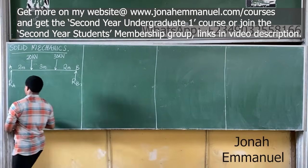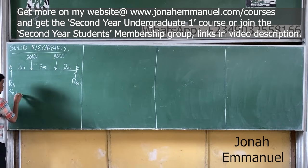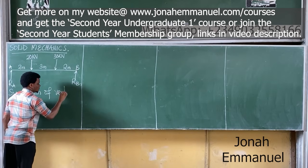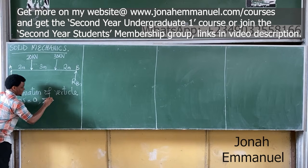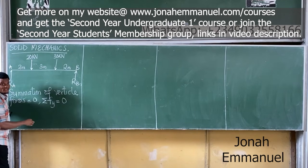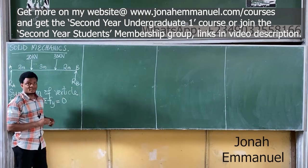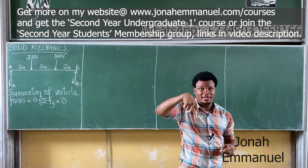Now, here, I will say summation. So I'm now bringing in the conditions of static equilibrium. So summation of vertical forces equal to 0. So I have sigma, summation. Vertical is Fy, right? Y is for vertical axis. Fy equal to 0. Now, in this stuff here, I'll put upwards, I'll put plus. What does that mean? Going up is positive. So if it's not going up, it becomes what there?